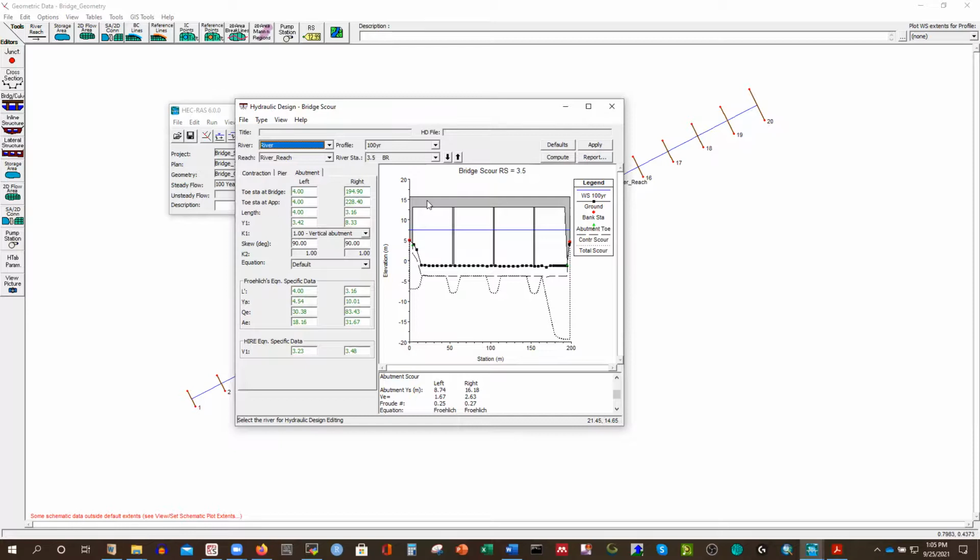So here, instead of doing that, what we have done is we selected the maximum, the highest high water level at the very downstream of the bridge, and then we already calculated the 100-year return period flow rate. Then we use only one value. We're giving only one value. If I have this one value, then what will be the scour? So that is another approach.